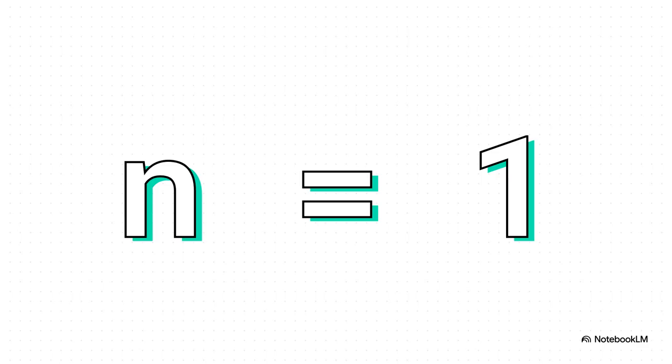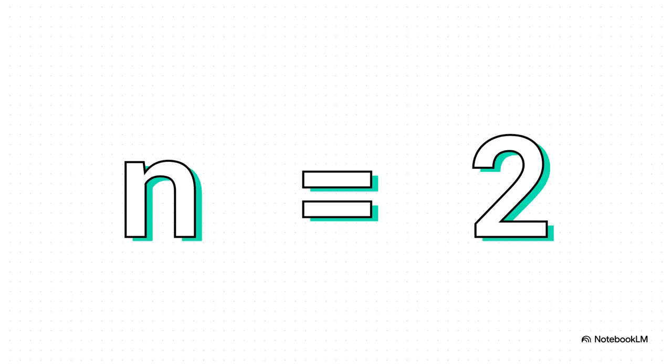It means your cell is behaving almost ideally, with very few losses happening right in the most important part, the junction. But if that N value starts creeping up towards 2, that's a huge red flag. It's the model basically screaming at you that something is wrong. It tells you there are probably defects deep inside the junction itself, and those defects are killing your performance. It's a direct numerical measure of the cell's quality.